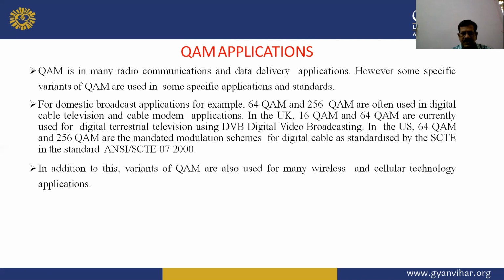In the UK, 16 QAM and 64 QAM are currently used for digital terrestrial television using DVB, digital video broadcasting. In the US, 64 QAM and 256 QAM are the mandated modulation schemes for digital cable as a standard by the SCTE in the standard ANSI SCTE 07-2000.